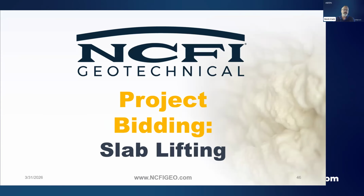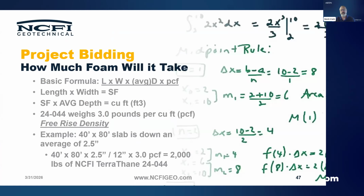I wanted to take what we have learned so far and apply it to bidding a project with slab lifting. This is just an imaginary project, but how do you figure out how much foam it's going to take? Well, the basic formula you can see: length times width times the average depth.